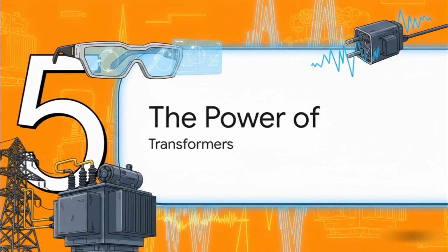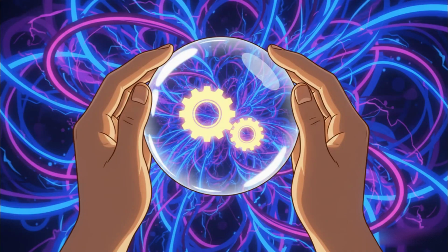Okay, theory is great, but let's apply this to a really important device, the transformer. These things are everywhere, from the power grid to your phone charger, and analyzing them used to be a real headache, but not anymore. Not for us. In the world of phasors, the really complex behavior of an ideal transformer all boils down to a single, beautifully simple number. We don't have to worry about magnetic flux or mutual inductance. It's all about the turns ratio.